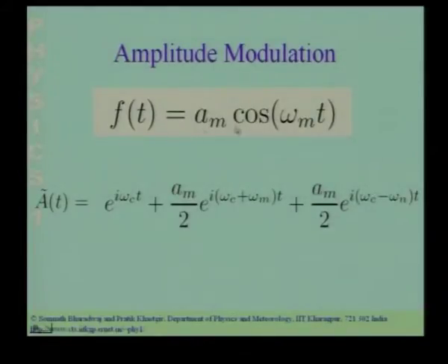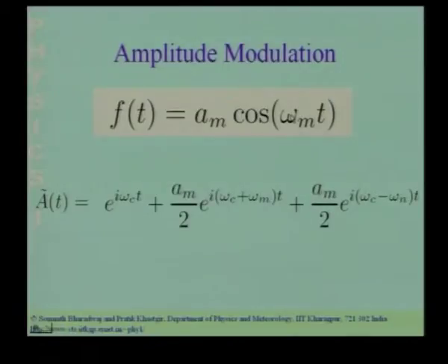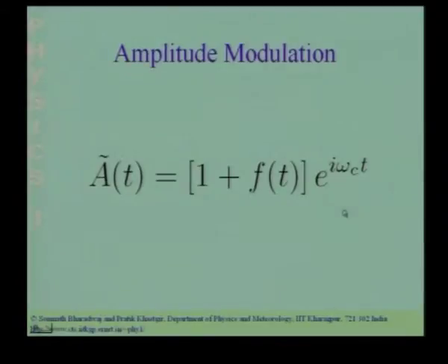So, this is the signal that is modulated onto the amplitude. The amplitude modulations in this case are sinusoidal oscillations at a different frequency, the modulation frequency. And we are going to assume that the modulation frequency is much smaller than the carrier frequency. So now the modulation is itself a pure sinusoidal at an angular frequency omega m, the modulation frequency, and it has an amplitude A m.